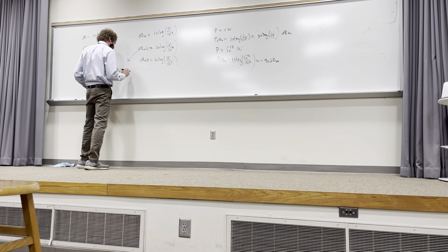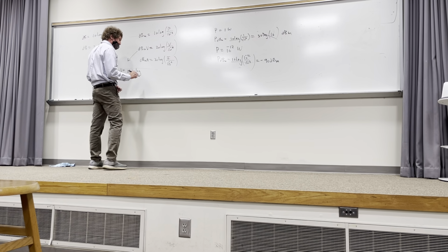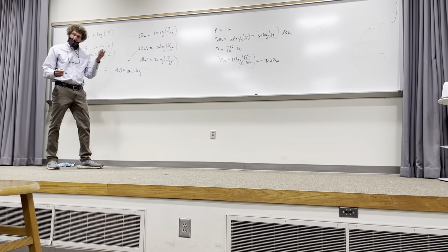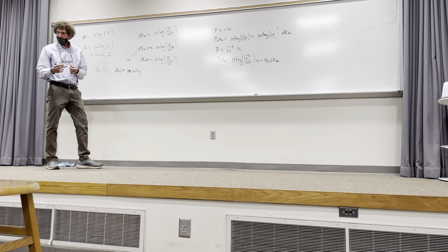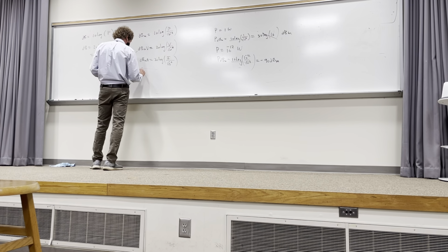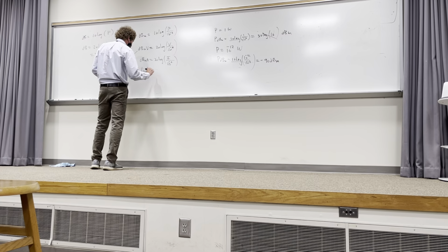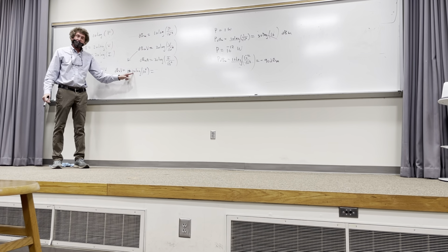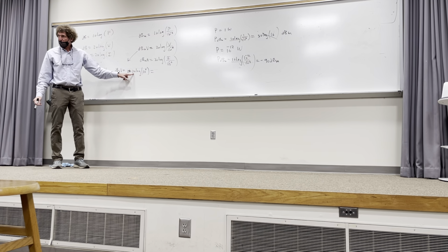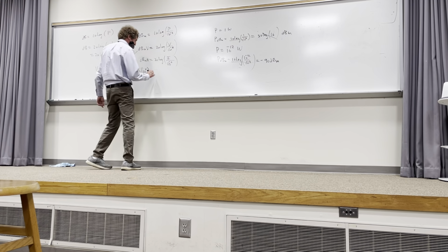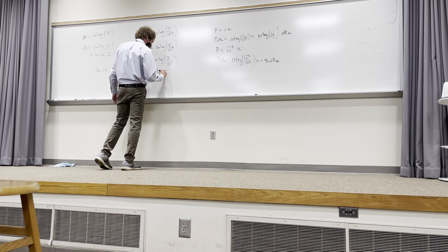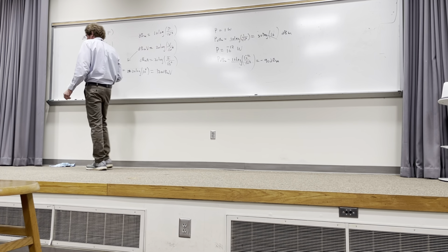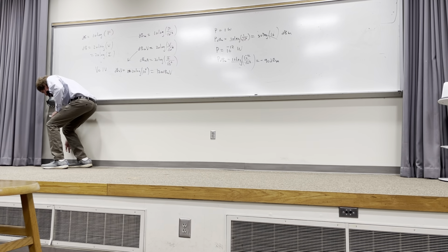Or not 10, 20, right? 20 times the log base 10 of 1 over 10 to the minus 6. 1 over 10 to the minus 6 is 10 to the 6, correct, class? So I'm just going to put 10 to the 6. And what's that? Just by looking. I take the 6 out in front, right? 2 times 6 is 12, 120 dB microvolts. And that's the way this stuff works. So don't let it scare you.